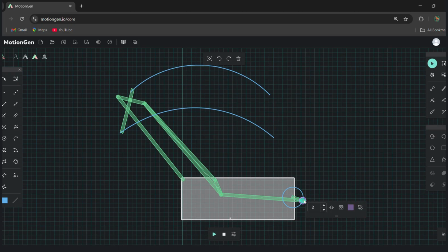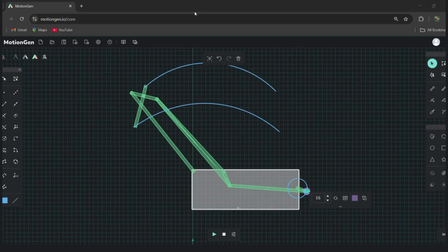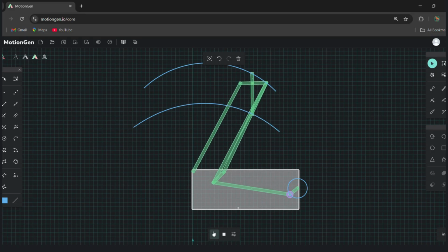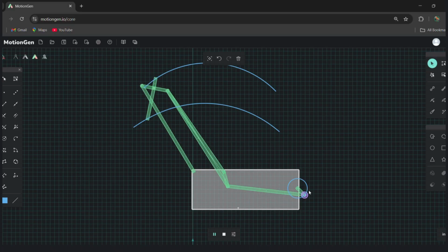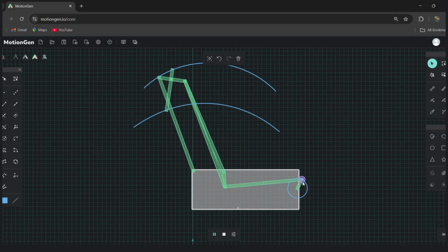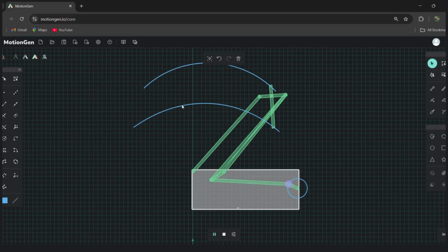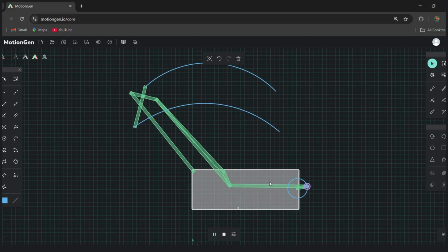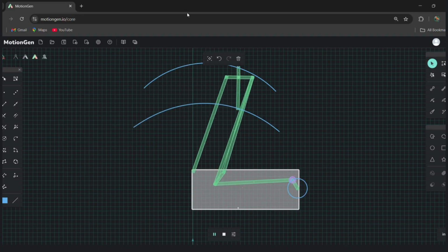First, we changed the RPM from 30 to 15, and now we can see that the wiping speed reduced proportionally. Then we can also change the crank length AO2 and notice that it affected the wiped area. Increasing the crank length increased the sweep area.